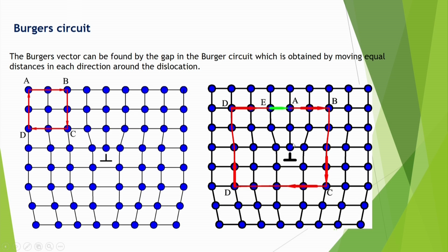Now we also have a term called dislocation density. What is the dislocation density? It is basically the length of the dislocation, because it is an edge dislocation. So how much length of the atoms is affected, that length divided by the volume. So it will have what unit? The length unit is centimeter and the volume is centimeter cube. So therefore dislocation density will have a unit of 1 by centimeter square. Don't say that it has, say, kg per meter cube or something like that. It is 1 by meter square, because dislocation density means dislocation length per unit area, and this is this one.